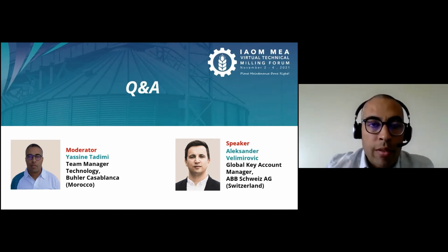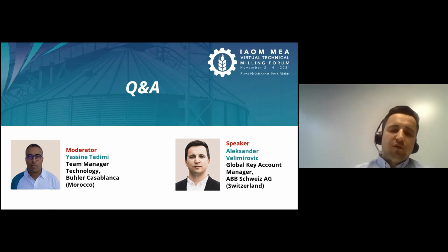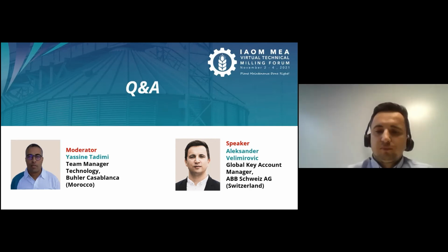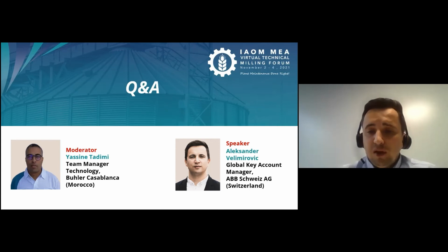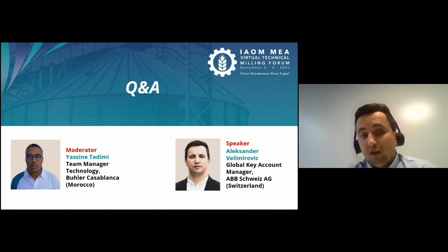Just to understand. If you have an old motor, for example one produced 10, 15 or 20 years ago, and you have a proper workshop, I know of cases where the new good quality copper and the winding possibilities of the service shop did a very good job, and the motor has the same efficiency or maybe better than the old low efficiency motor.